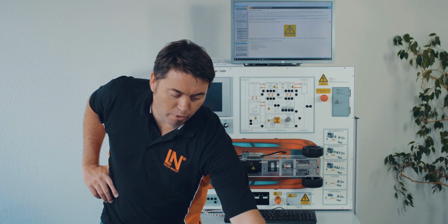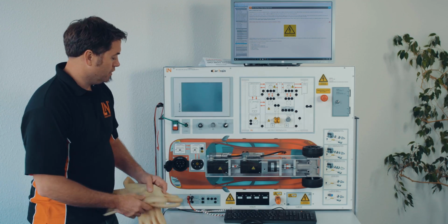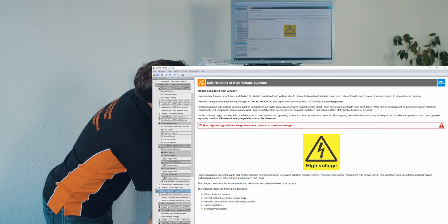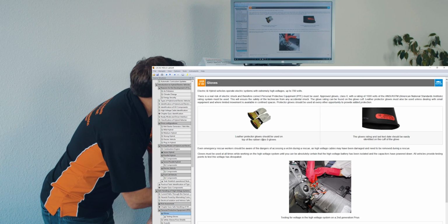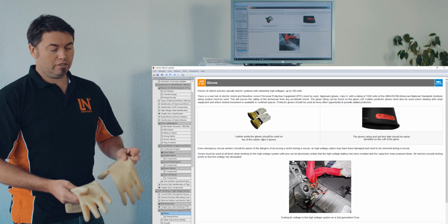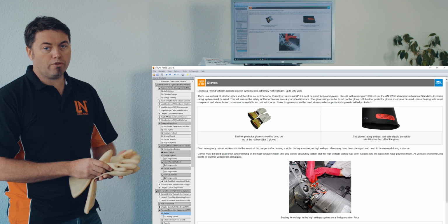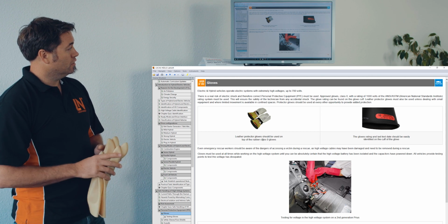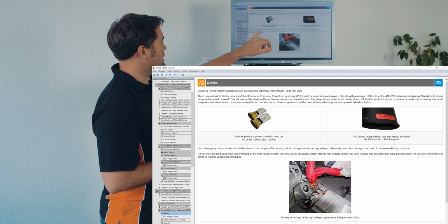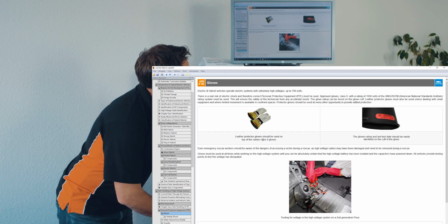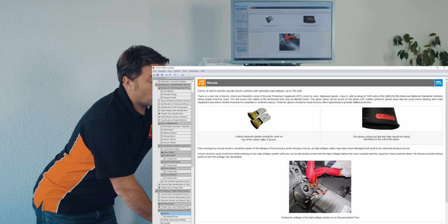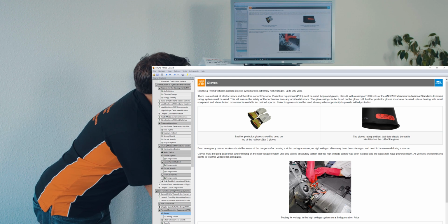But yeah, it really needs to be careful. We also need to be aware of all of our safety gear. So if we go through some of the different PPE, gloves will be dependent on where you are around the world. For the American standards, we've got the Class 0 type gloves, and they're rated up to 1000 volts.